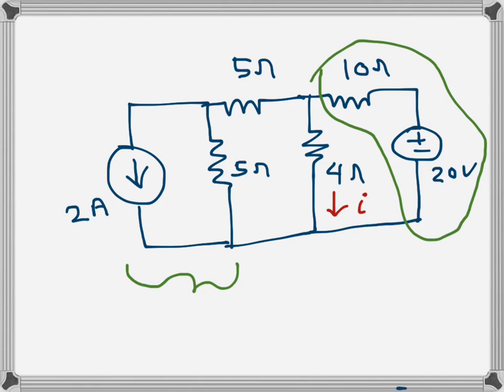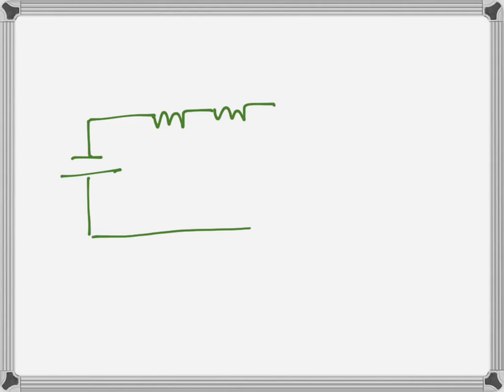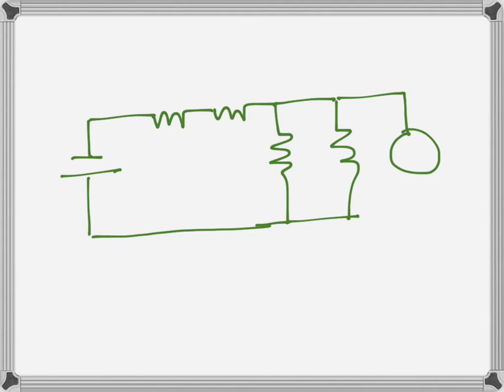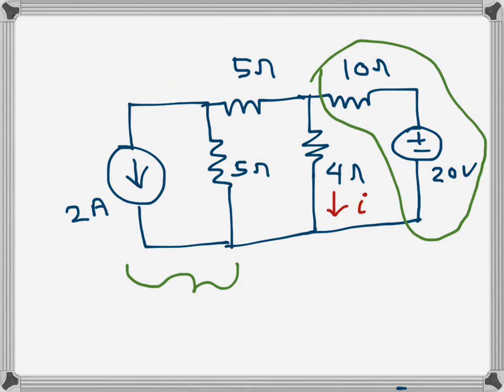So let's do that. When I do the first one, it becomes a voltage source. The polarity will be downwards, and the resistance I can draw here. Then this one becomes like this, and the current source. I will come to the values next, but this is 4 ohms. It will remain intact, and this 5 ohms will remain intact, and also the resistances. Even after the conversion, the resistance value will be the same, so they will remain like that.